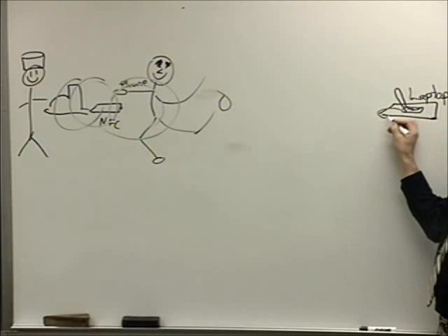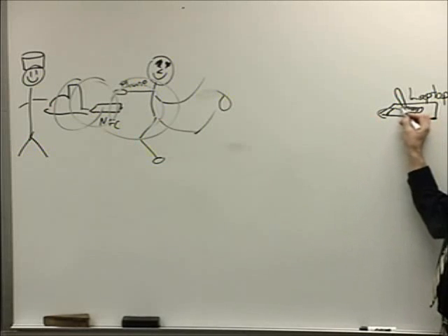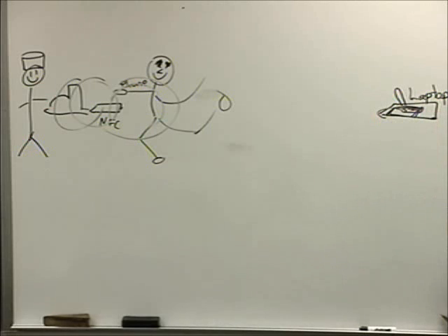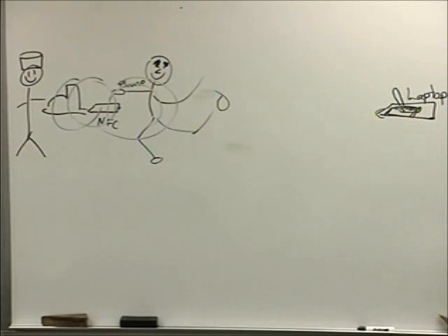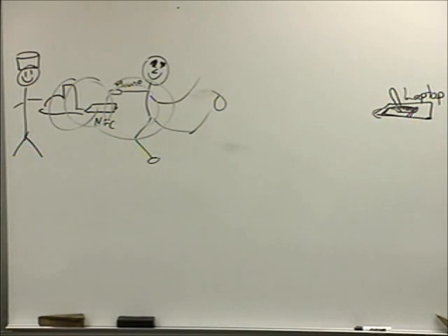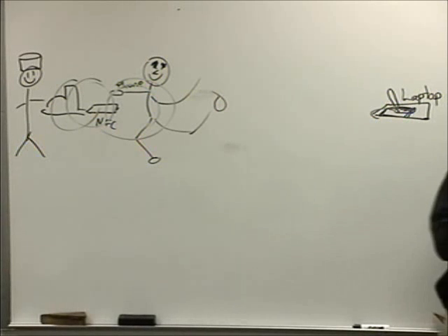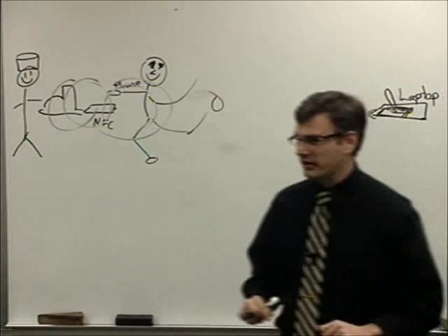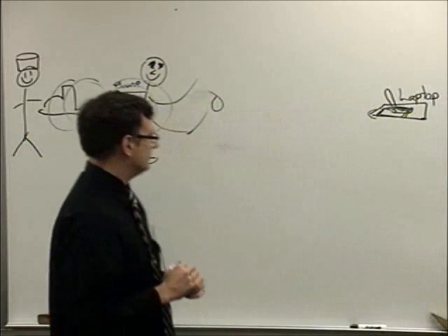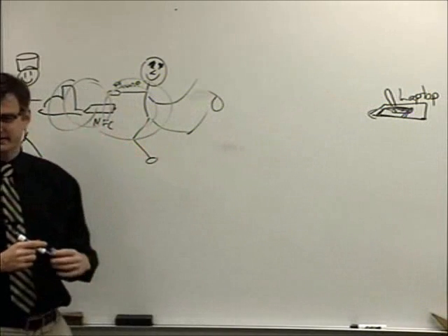And so you have a coil of your own with a very large aperture collecting flux, monitoring the transaction. And you've tuned it with capacitors so that it resonates at 13.56 megahertz. But it's too far away.